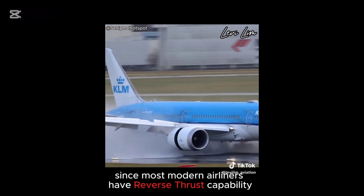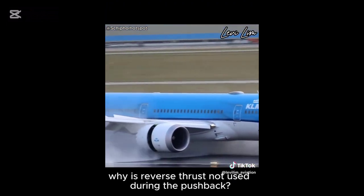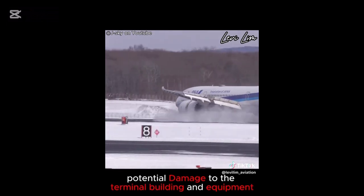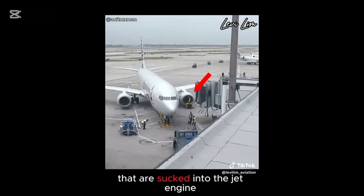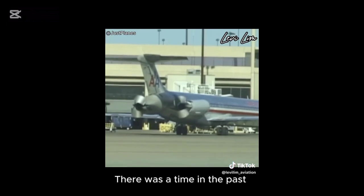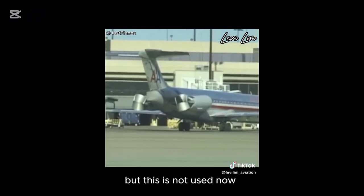Since most modern airliners have reverse thrust capability, why is reverse thrust not used during the pushback? The reason is the resulting jet blast would cause an increase in noise, potential damage to the terminal building and equipment, or even cause injuries to the ground crews. Foreign object debris (FOD) sucked into the jet engine may also cause unwanted damage. There was a time in the past when reverse thrust was used for pushback, also known as a powerback, but this is not used now.